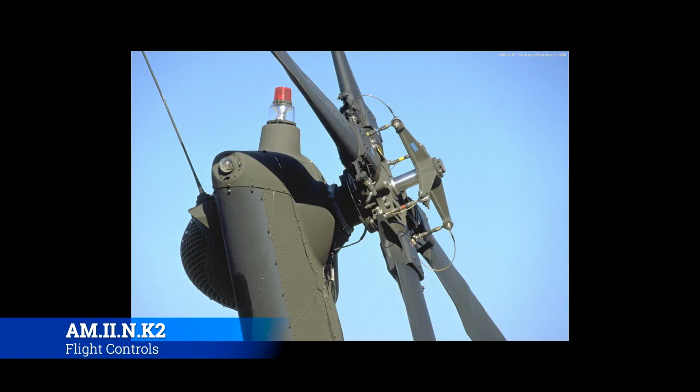Now, it accomplishes this directional control by changing the pitch of the blade. So you can really think about the rotor pedals as like a collective, but just for the tail rotor. When you press on the tail rotor pedal in one way, it's going to pull on the blades to get more pitch, so that way it increases the anti-torque force being pushed on the body of the aircraft to overcome the torque force of the main rotor.